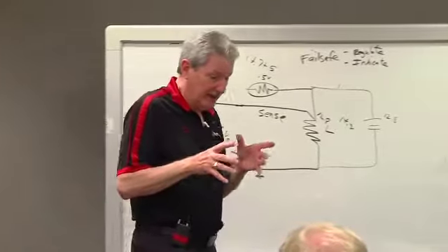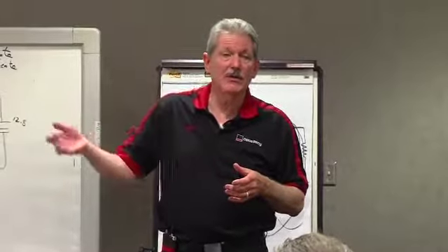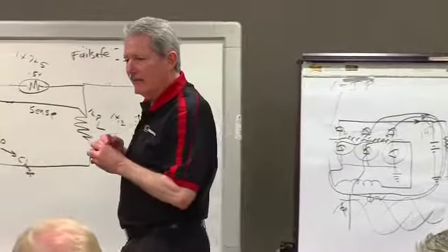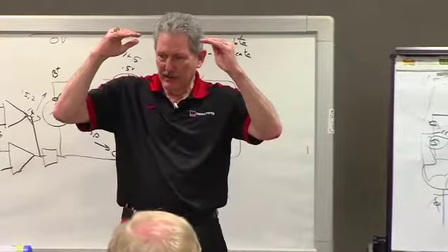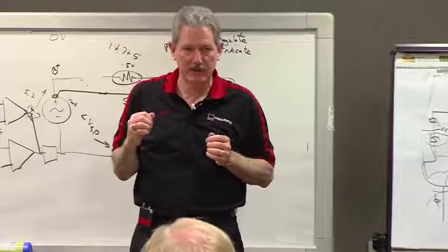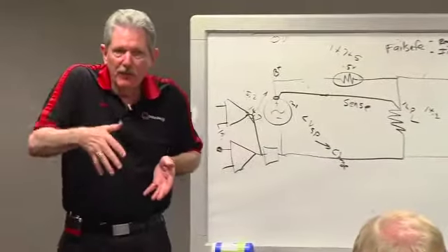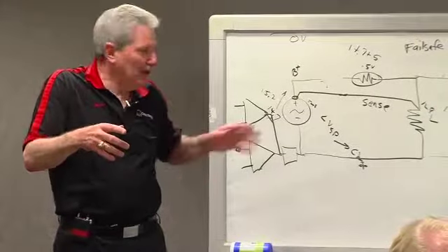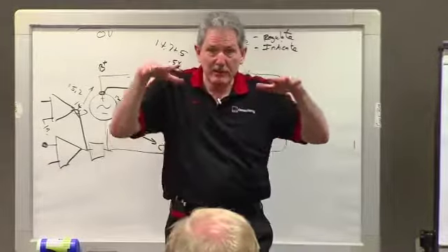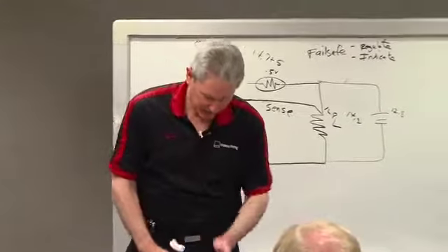Now we have a 1985, 86 alternator that can put out 100 amps, which was phenomenal back then. We've got an overvoltage and a fail-safe, but we also want something that indicates if we have an undervoltage condition. Let's say one of our diodes is bad on the rectifier. So it goes to full field, but because I'm losing a third of the current, my voltage is going to drop. So the answer to that is to have an undervoltage.